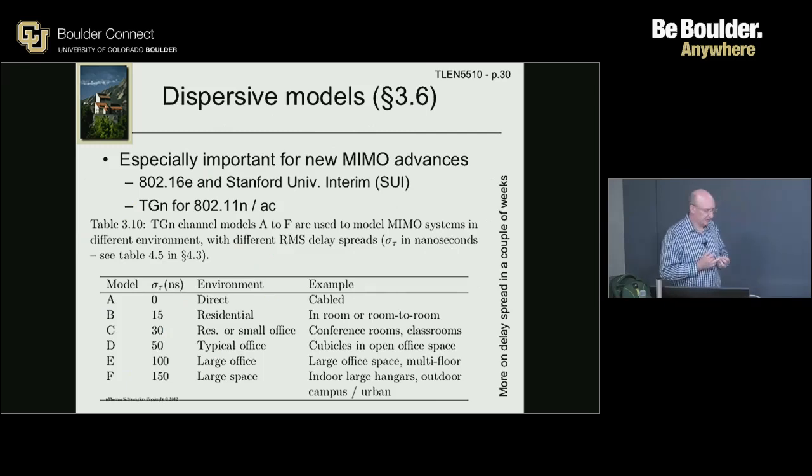So all these models we've seen are in a way fairly simplistic, right? They measure the power as a function of distance. You have one transmitter, one receiver, and there's distance, and a path loss exponent tries to get rid of all the other shadowing, small scale fading, all the stuff we'll see next week, which I sort of averaged out. That's all very well and good in a first approximation, but in many cases it's not good enough, especially if you think about MIMO and other things.